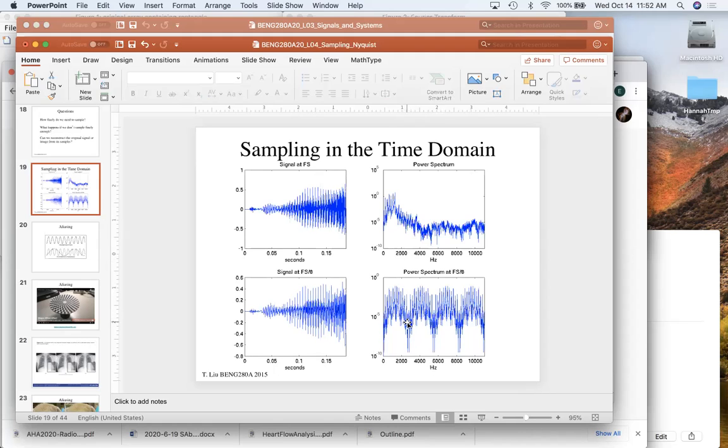These frequencies start adding in, and so you lose all of this information. If you know ahead of time you've got information out here, then you just need to upsample to make sure that you get that, if this stuff is important. Sometimes all of the information you need is actually contained inside these frequencies. You can just filter the signal and get rid of these components out here that are unnecessary.